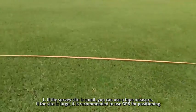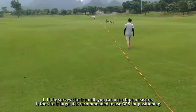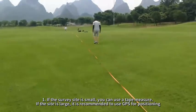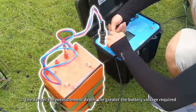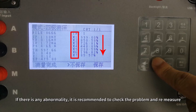1. If the survey site is small, you can use a tape measure. If the site is large, it is recommended to use GPS for positioning. 2. The deeper the measurement depth, the greater the battery voltage required. 3. The measured apparent polarizabilities M1 to M7 are generally decreasing. If there is any abnormality, it is recommended to check the problem and remeasure.